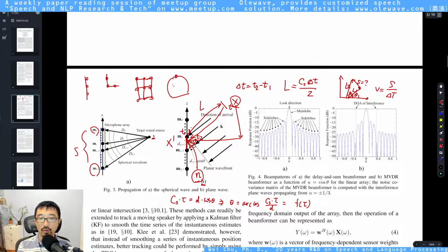So say I have a microphone array on different locations of a sphere, okay? Different sorts of arrays. What people do this for is that they're trying to use different ways to better estimate the original signal X from the captured signal X prime. And X prime is a vector. So it goes from the signal captured at the first microphone to the last microphone. Okay, it's a vector.